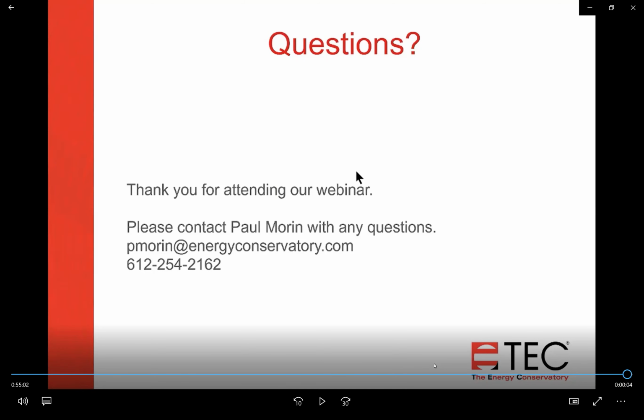I know the 300 or the 360 RESNET 360 did allow you to tee the supply and return together, but I think they're going to retract that. We've had some discussions with them about that, and it sounds like they're going to. We, as the manufacturer, recommend only measuring on the supply side, and the closest supply register is a good location.